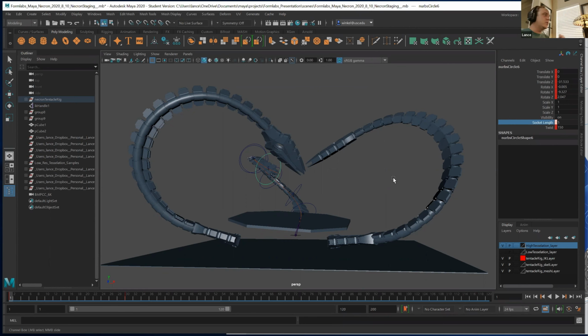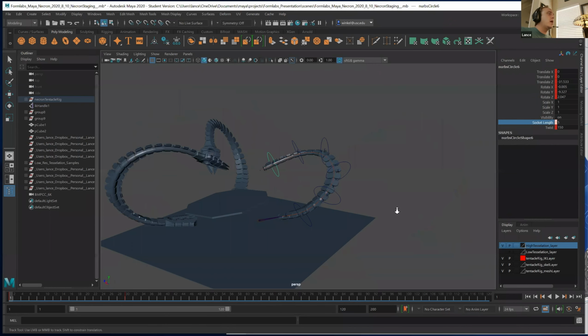So in Maya 2020, which is the current version of the product, there are two ways to get your model into a format that will go to Preform. STL is working, but they have changed where that plugin is. OBJ is working, it's the same plugin. Now, we're gonna do that right now, but let's say I wanna take a model and export it,